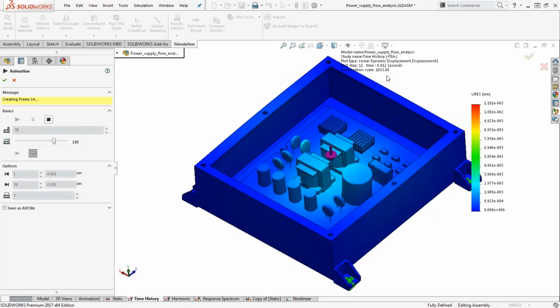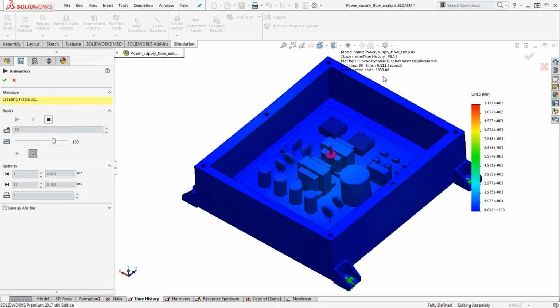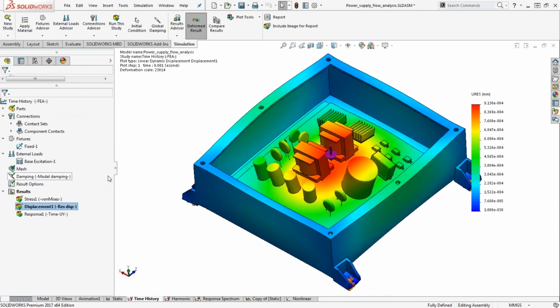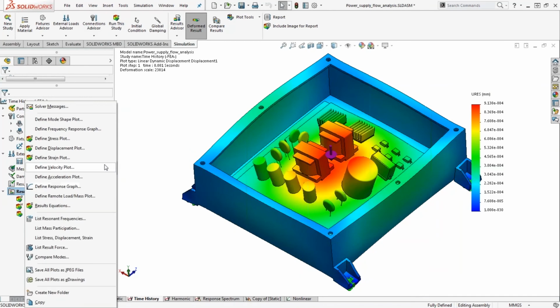If you point your attention to this cloud message here, you see that I'm looking at the stresses now at 0.019 seconds. I can go into the stress results and view the stresses at any time increment that I define within here. So if I do it at 11 milliseconds there, then you see that I can get my results there based on that time step, or again, I can animate this and you see how the results are changing as a function of time.